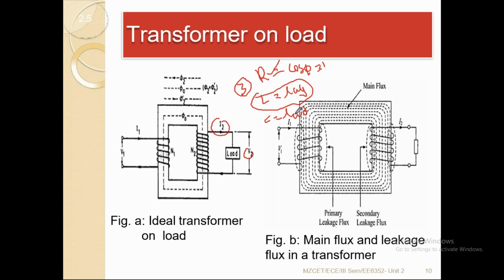How can we say leading and lagging? If you use a resistive load, you already studied in network analysis, right? The characteristic of a resistor is linear. Linear in the sense that whatever amount the voltage varies, the same amount the current will vary. So here you take I and here you take V. The current and voltage are directly proportional, and these two parameters are in the same phase. That's why the resistive load always has unity power factor.